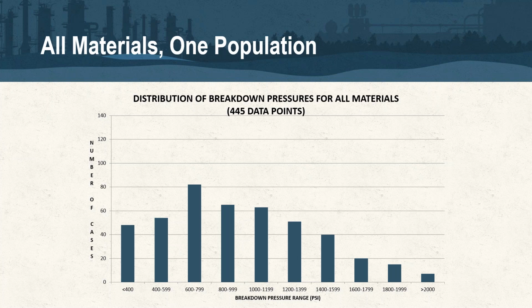and permeability. And what we typically target when we do an injection is initiating a freshwater test on those intervals. And where we assess a go or no-go on that specific interval is initiating fresh water. If we reach that upper limit of about 1,200 to 1,400 psi and nothing happens, it just holds, that particular interval is believed to be non-producing and non-effective for the purpose of injecting a slurry.